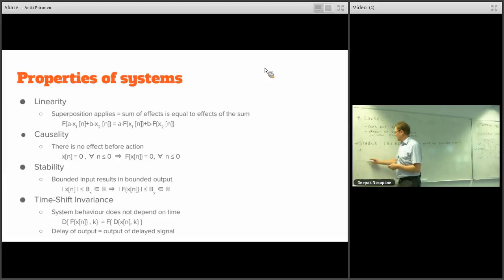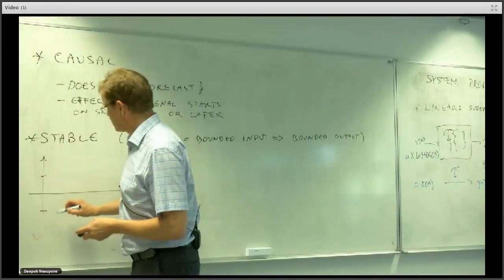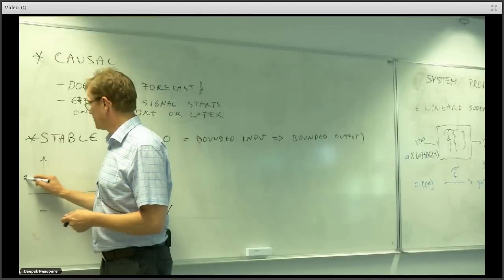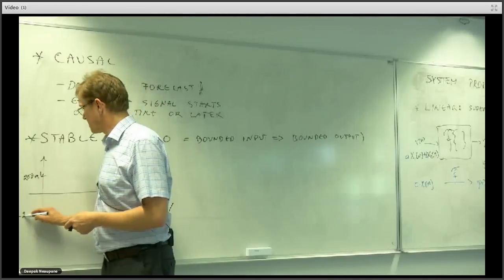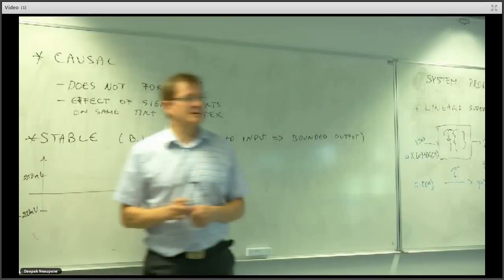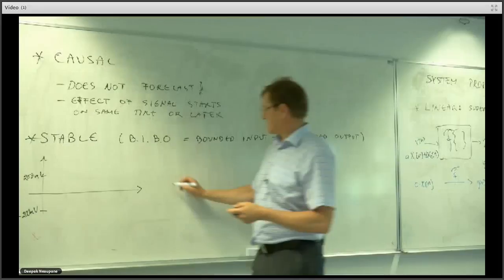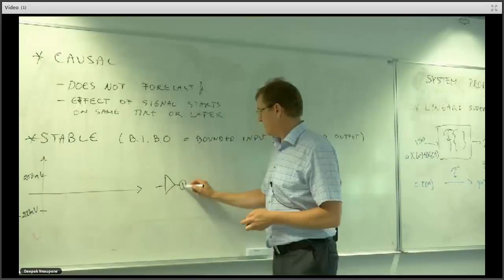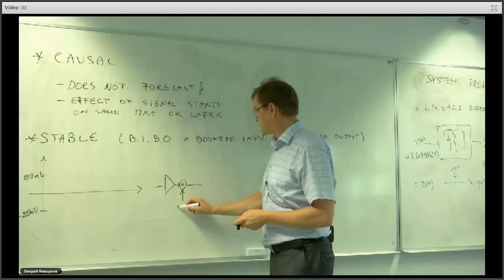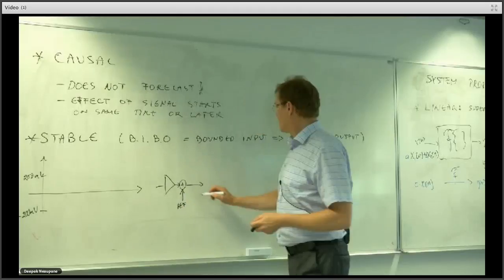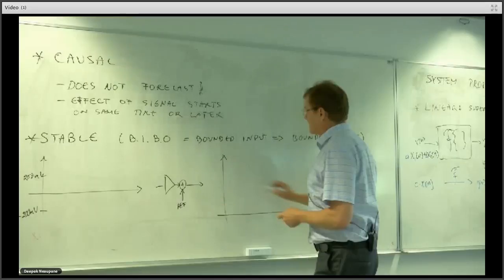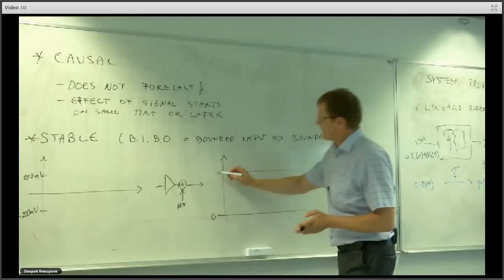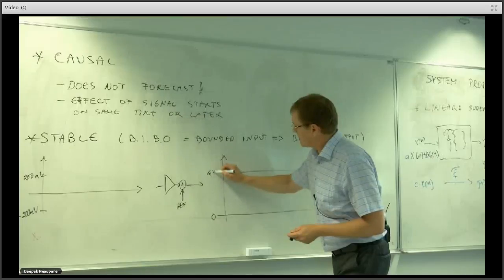So on systems, a good audio system is a bounded-input bounded-output stable system. If we think of microphone levels, say between plus and minus 200 millivolts, you design an analog system such that the gain and the level shifting, or the reference point of the system, maps that data to the 0 digit and the maximum value of the A to D converter.